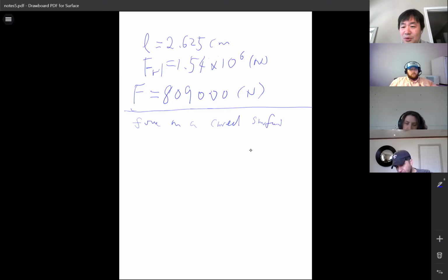They call it replacement, right? The object replaced by the water, same volume. Then if the object is heavier than water, the object will sink. If the object is lighter than water, it will float. That's why you have buoyancy force. But that's not the reason. That's the observation, right? Actually the reason is what I just said. The bottom half of the surface experiences a higher hydrostatic force than the top half of the surface of that object. So the difference is the buoyancy.